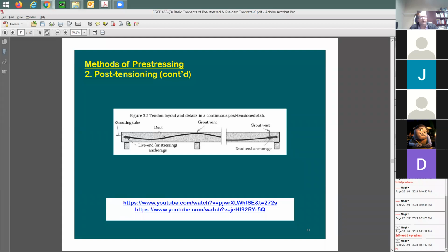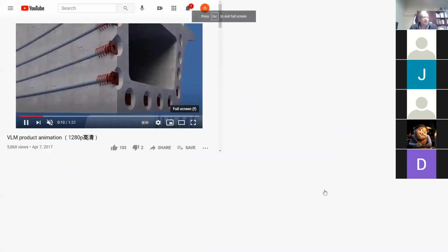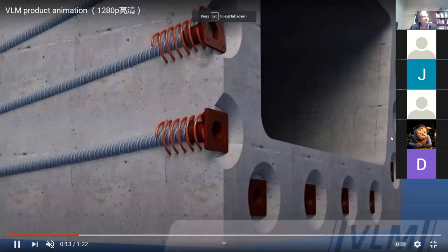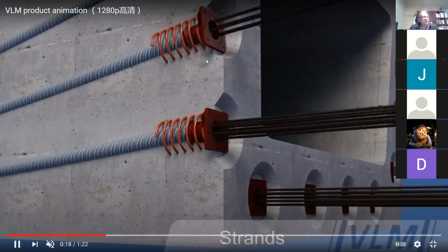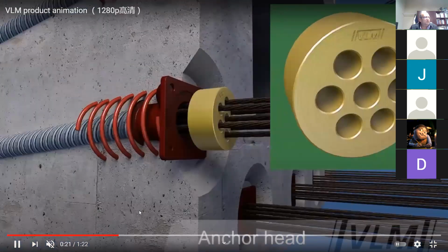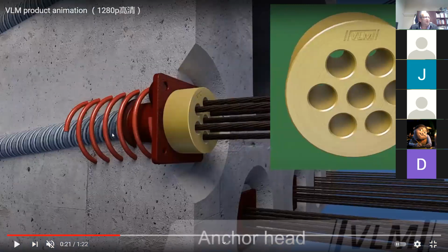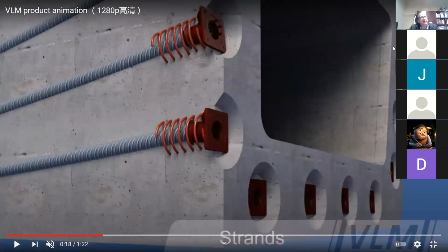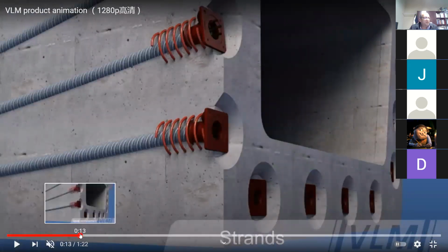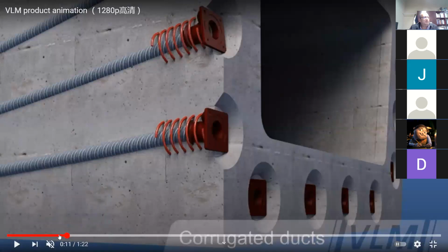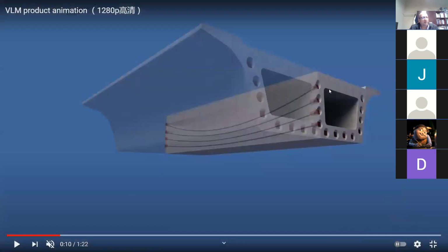I want to show you something quickly about this pre-stress. I like this illustration. This is going to be precast pre-stress, showing the cable location. You put the cables, and look at this. It's going to be the cable or the conduit, right? It looks like this corrugated sheet, and it comes with grease and everything. So you bring this precast, which is going to be part of a box section for a bridge. Here's the way it looks, and here's a cable. It comes like this with this drape, right?